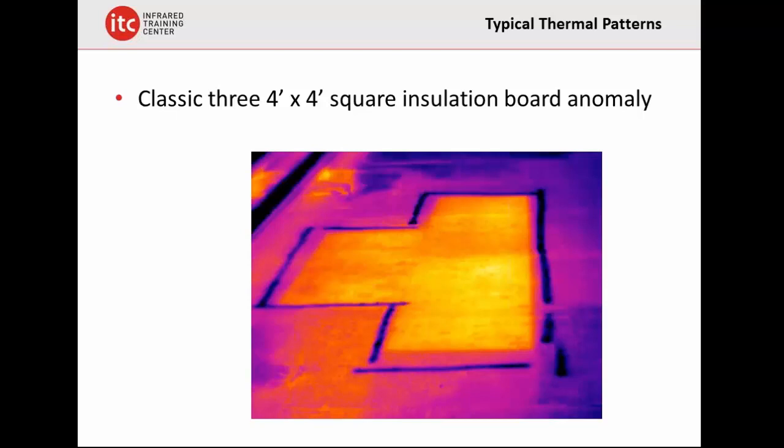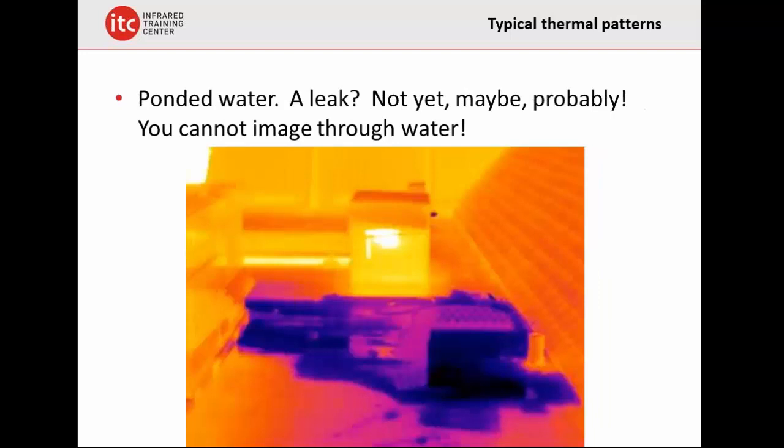Absolutely. If you get up on a roof and you see a regular hotspot, and they're all lined up, it could be the ballast of lights, like in a warehouse. So you have picked that up. Absolutely. Matter of fact, I have that in my roofing course, where we can see a dot going right down this warehouse, and it's actually the ballast from these big sodium vapor lights sitting in this warehouse. So that's something for people to look out for. Yeah, it's a false indication. We have a lot of false roofing indications.